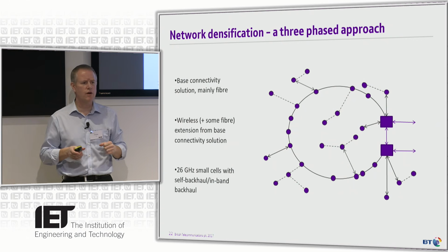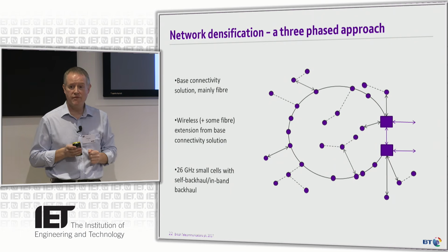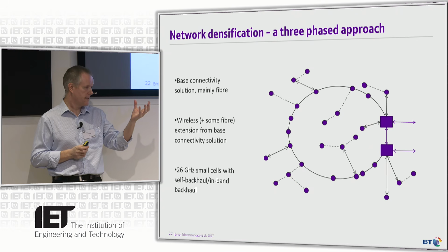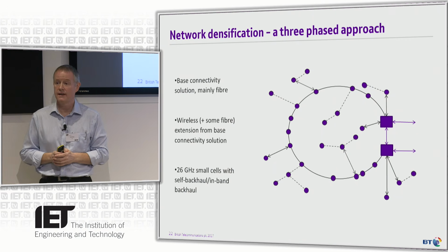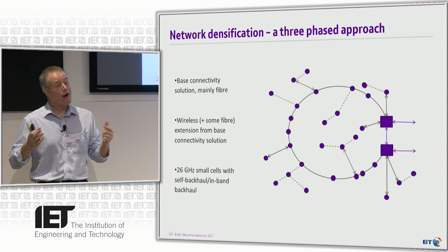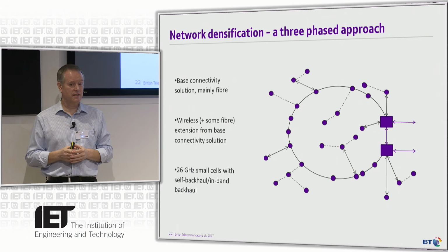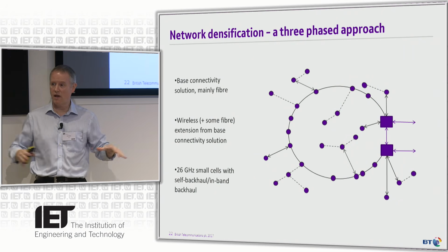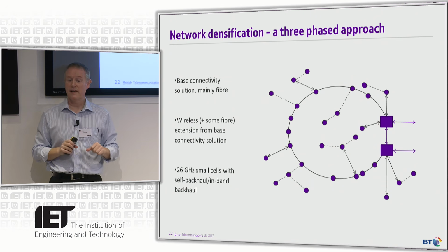But then what happens when we really do go for ultra dense networks with 26 gigahertz? Well, 26 gigahertz, we've heard a number of references today to self backhauling. I am a believer in that. I think it's going to be a very efficient way of dropping a site in. There's a few ways it could happen. There's 3.25 gigahertz of spectrum in that 26 gig band, as we call it. So operators may have enough spectrum to allocate some for backhaul, some for radio access. Or actually, with the spatial multiplexing benefits of massive MIMO, potentially there's a reuse probability as well for radio access, possibly not over the whole 360 degrees of that cell or whatever angle it's covering, depending upon the antenna array. But potentially in some areas, whilst directing backhaul in another area as well.